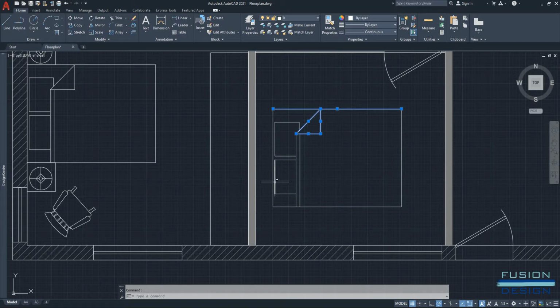from the other. A single bed is 900 millimeters wide, so I'll draw a line from the corner 900 millimeters down. Type in L, enter, find my corner point, hover, type in 900, enter, and draw that line. Now I'll type in TR spacebar and I'll trim off the excess lines.